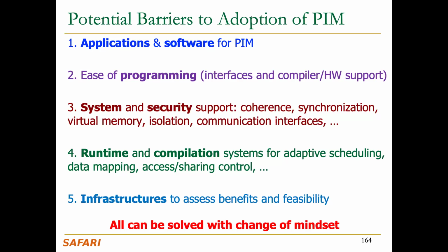The next question. For these within-DRAM computations, for example, the majority function that you described, do you end up wiping the data that you're computing on? Absolutely, yes. I didn't go into a whole lot of detail. I gave you the key idea, but once you do the majority, you're actually wiping out all of the data because the bit line is affecting all of the cells. You're actually writing the data back into all of those cells. So what you really need to do is combine this with RowClone: first, copy the data to a location where you can compute on it. What we do in our implementation is have a special part of the DRAM array that's specialized to do this sort of computation, maybe 3 rows or maybe 10 rows.